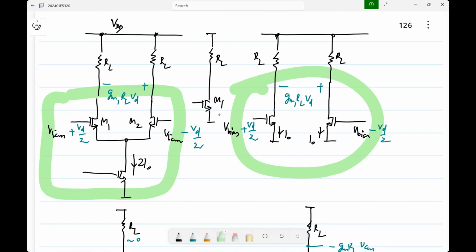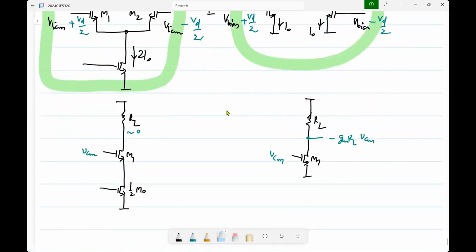Now, of course, you will use blocks like this and you may want to have some common mode rejection. So this is where the problems of the circuits of the type you saw in the assignment come in. The differential pair has its common mode rejection, but let's say we were operating in a case where the amplifier part has no common mode rejection at all. It treats differential and common mode circuits equally. What you can have instead are load structures which behave differently for differential and common mode. So one particular example is the following.